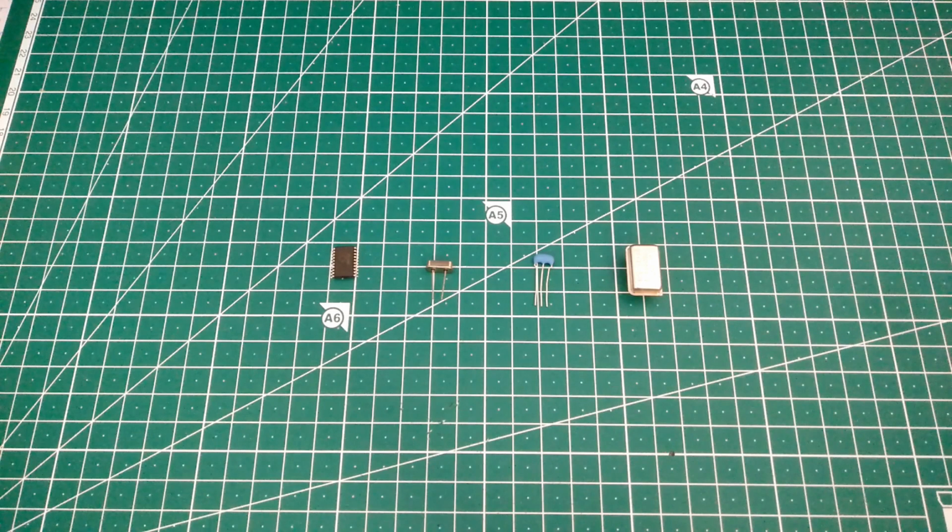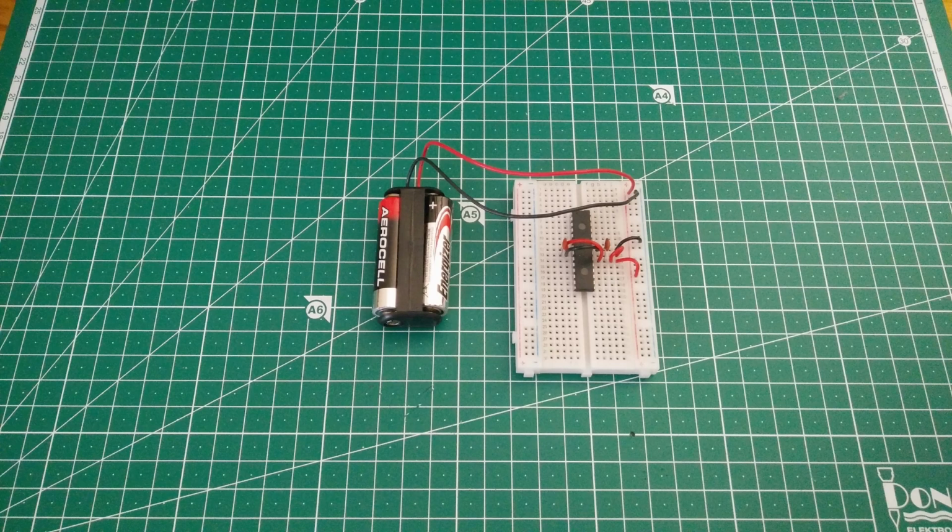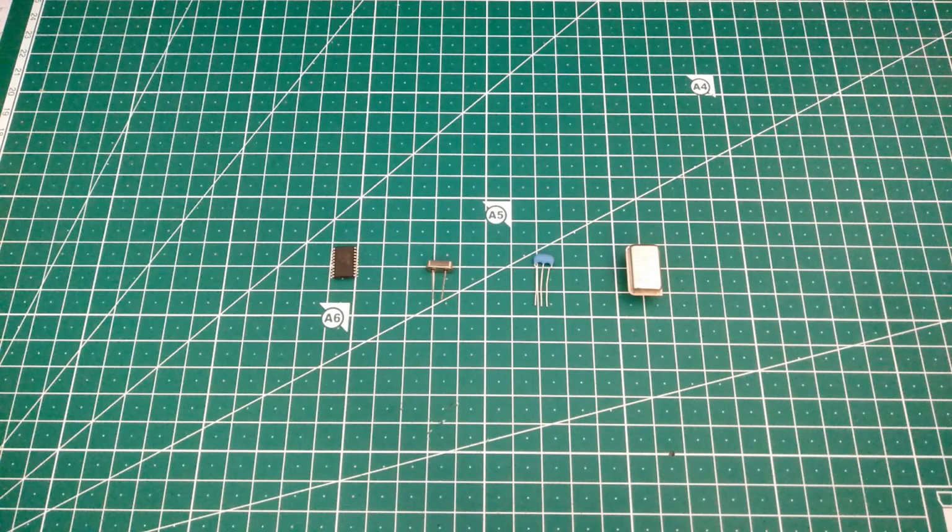So, how do you use this in practice? Well, we will show you that by using the simple circuit with an ATmega328 microcontroller, which we've shown already in the first video of the series, and then on top of it we will install each different clock provision option, show you how the hardware looks, how you configure the microcontroller to use them, and show you the things in operation. As that video already thoroughly covered the internal oscillator, we will not cover that here, and instead we will start with the crystal.